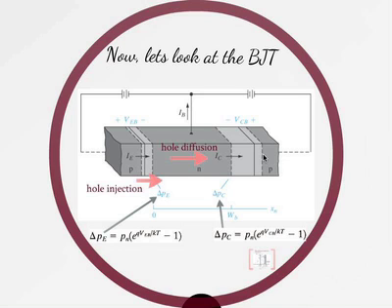Okay, so let's step back a second. Think about the collector and base. Is the junction forward biased or reverse biased? It's reverse biased. So what should the collector to base voltage be, positive or negative? What is the collector, P-type or N-type? In this case, look at the picture. Yeah, it's P. So what should the collector to base voltage be? Negative. Okay.